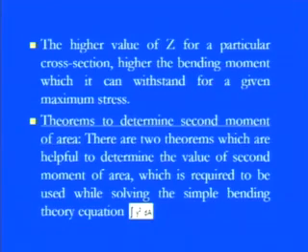That means if you want to find the bearing capacity of the beam, first of all our main intention is to find the maximum value of the section modulus, and once you know it, you can say we can go up to this maximum bending moment, with the corresponding change in the bending stresses. That is why Z, the section modulus, is a very important parameter to design this beam for loading conditions.